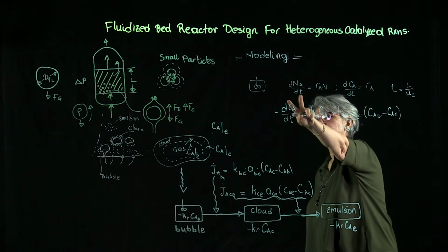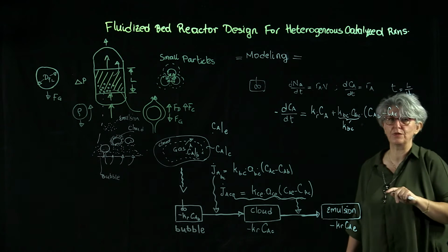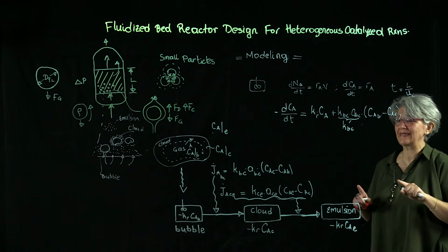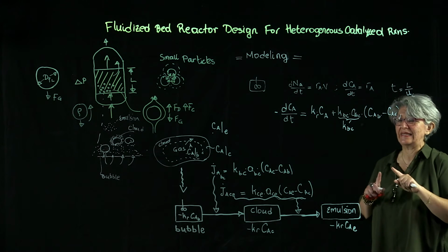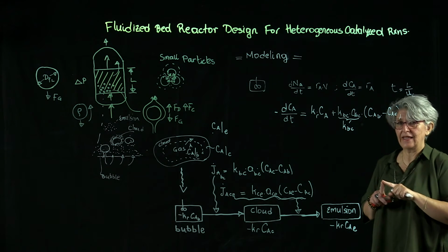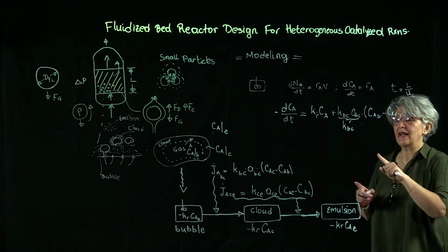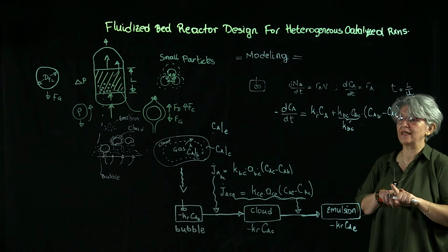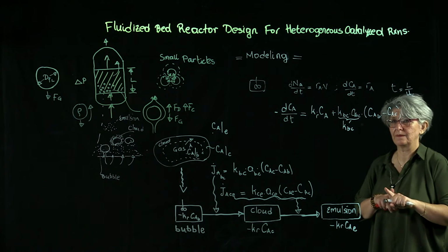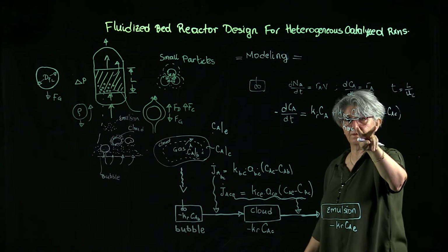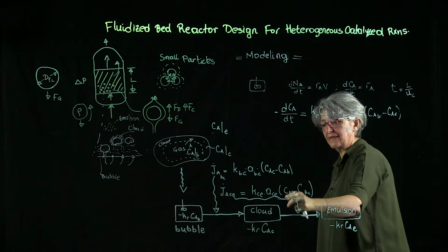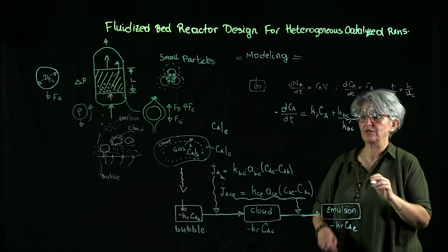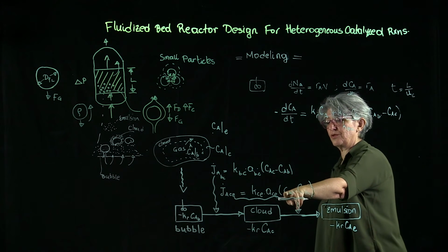So we no longer have the unsteady state term in the cloud. We're going to treat cloud as a CSTR, a well-mixed reactor, intaking species A from the bubble through this transport term and transferring species A to the emulsion through another transport term.